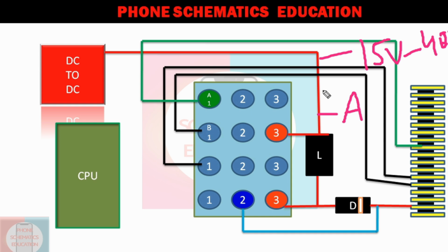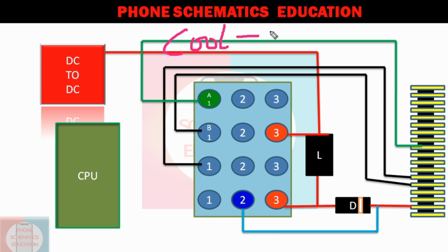Clear? Also, you must have noticed that many times the connector pin where the anode line connects is burned on these points, the anode points. Basically the reason is that this is a high voltage line. I hope you get my point, what I taught you. Now, how do we check the anode line step by step? How do we measure it in diode mode? There are two types of testing. First, cold testing.